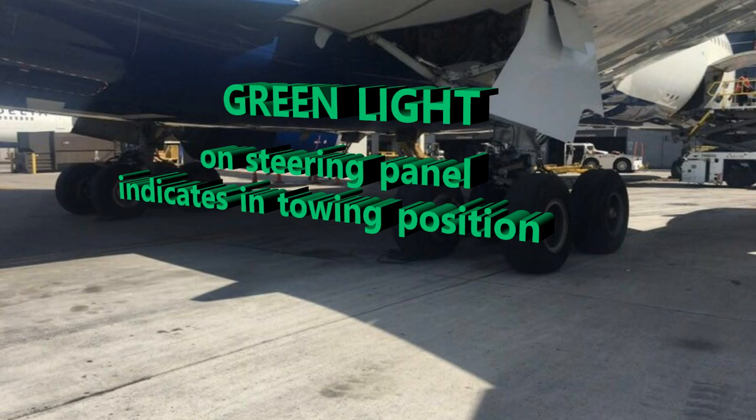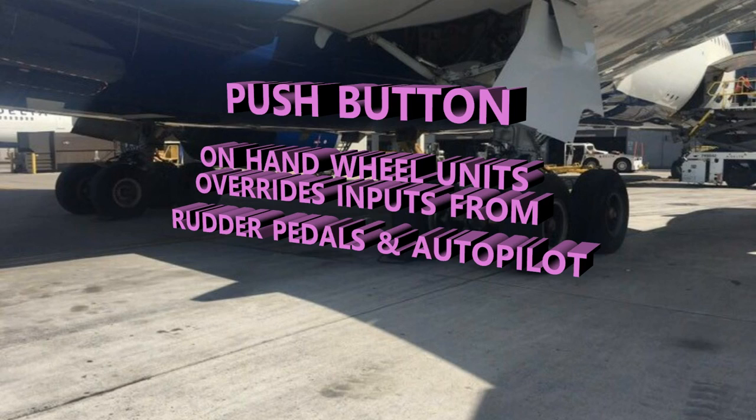Like I mentioned before, there are the hand wheels, which are your primary steering inputs. There's a push button on the hand wheel units that, when pushed, causes the control system to disregard the commands coming from the rudder pedal during any pre-flight checks. It also prevents any nose wheel tire scrubbing. So that's just details on that.